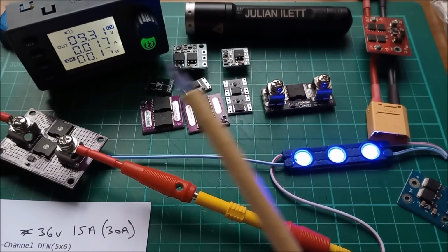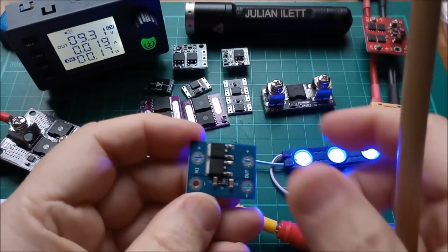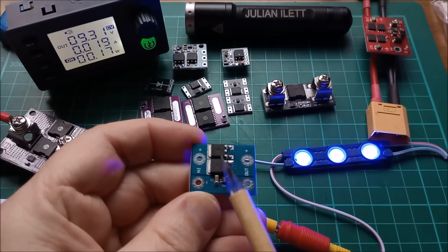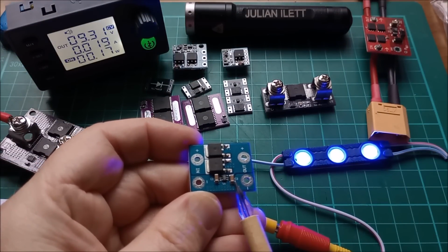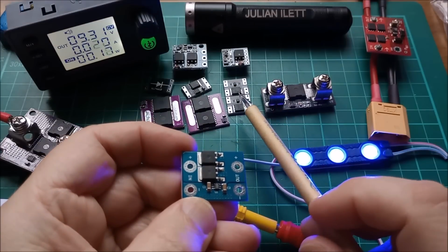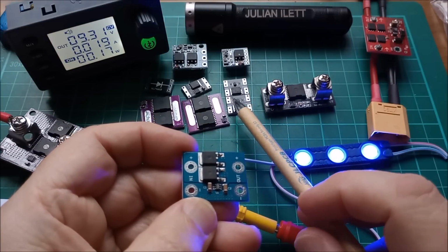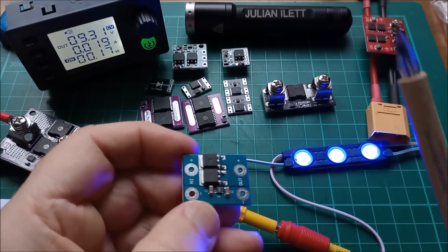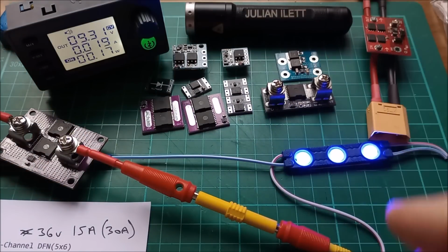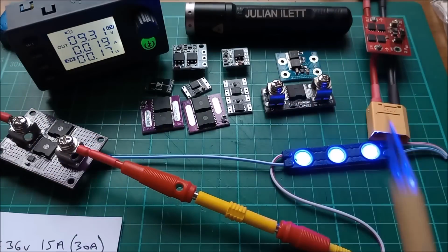These are the modules you're likely to find. I'm going to have another look at this one. These are definitely P-channel MOSFETs because I've checked them, but the chip is scraped, so I can't see what it is. But yeah, these are capacitors, which is different to the two resistors on the 0401 P-channel ideal diode controller. So not entirely sure what that is, but that's ideal diodes from AliExpress.